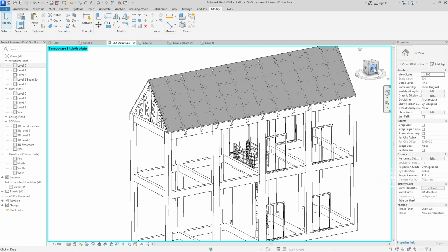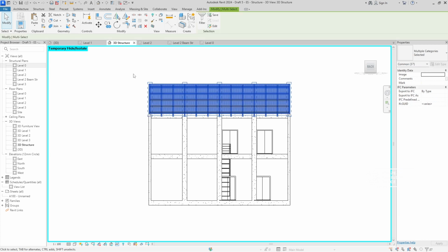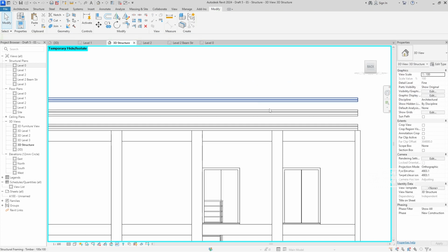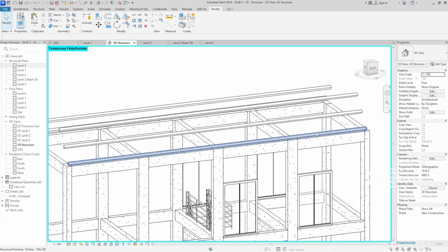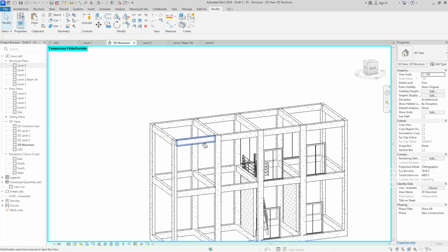So before we continue to the structure drawing, we need to analyze whether it is adequate, and also we need to get a fixed number of rebar reinforcement that we need for every section of columns and also the rectangular beams that we have created. So to go on with this, let me hide this one, and this one.